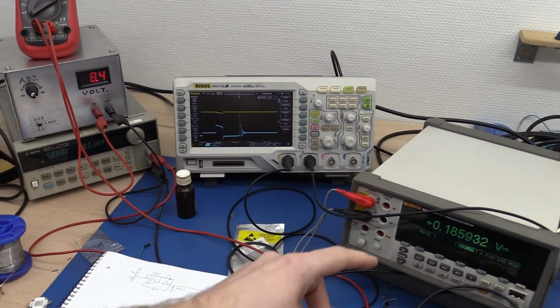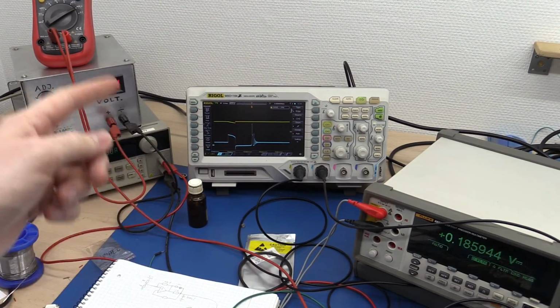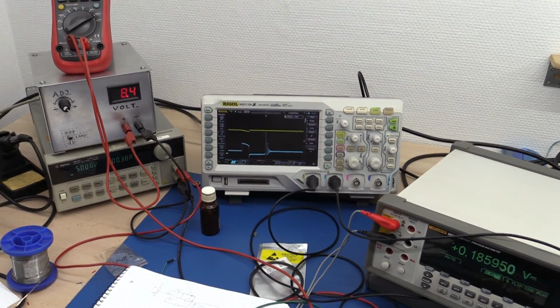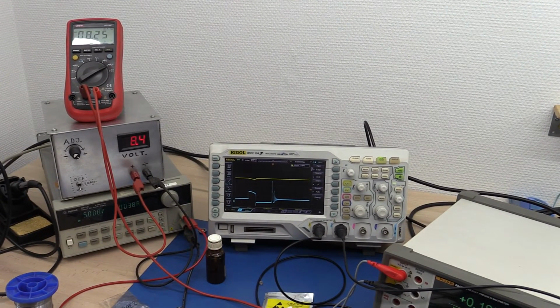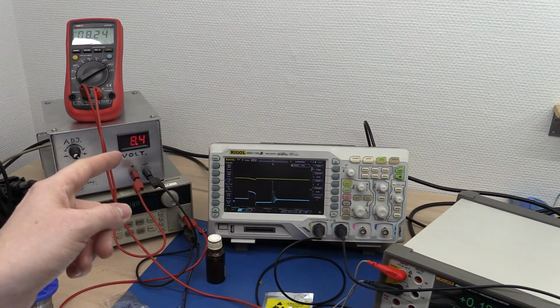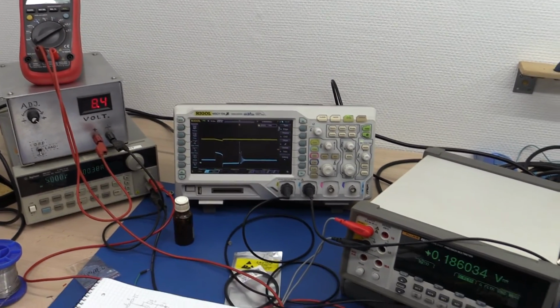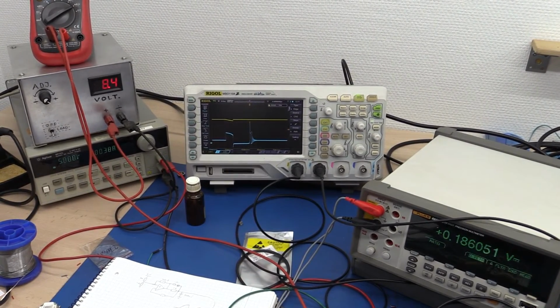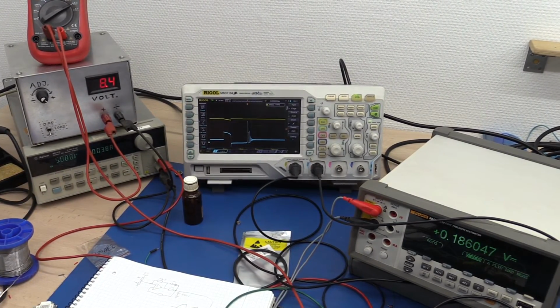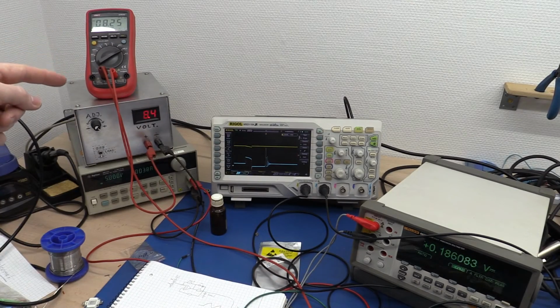If we compare that to 18 milliamps for the LED, you can see that we're definitely better than the linear regulator. It is still not a very good efficiency though. Remember, the voltage drop across the LED is around 1.8 volts and 200 millivolts across the resistor. So that gives us roughly 2 volts. If we say our current is half but our voltage is 4 times, that would give us an efficiency of about 50%.